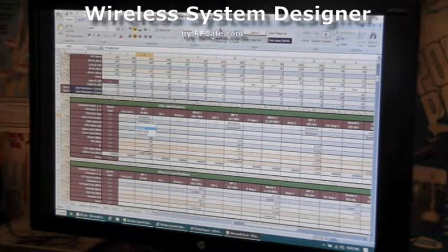I put a practical limit of minus 250 dBm is the lowest power, again, just to keep things from getting ridiculous, because if you have a really high order filter and you're way out of band, you could easily end up with a couple thousand dB of gain, and that's not realistic and not useful, so I put a limit on it. And then Butterworth and Chebyshev, so again, standard textbook filters.